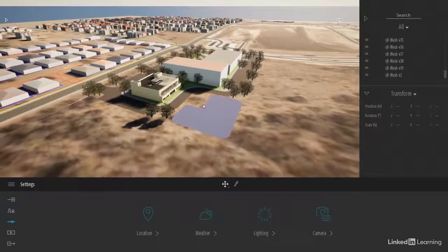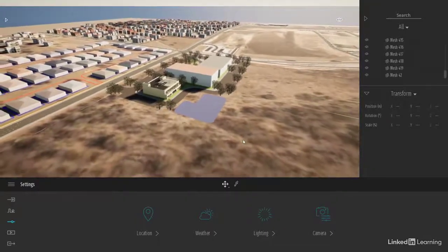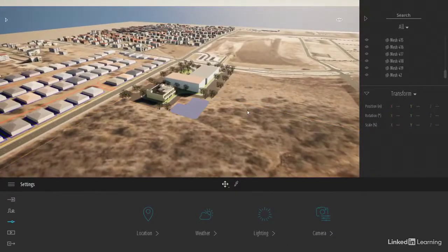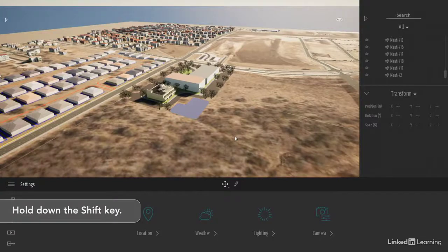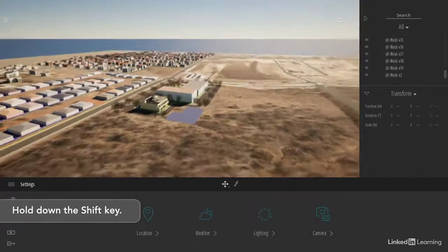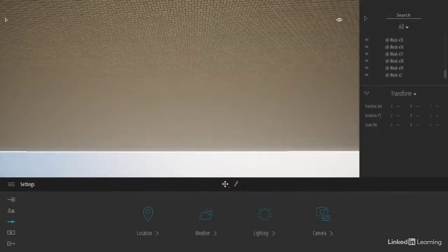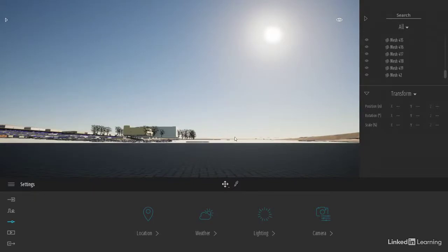In order to have a terrain that you can model or sculpt or do anything like that, we need to add it. Now, again, I'm just going to grab my middle mouse button, holding down the control key, and I'm looking underneath my FBX model. Do you see this weird kind of paving here? That is the starting ground. If I click on it, you see it's there. We've moved it up to 225.